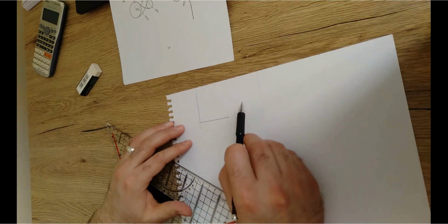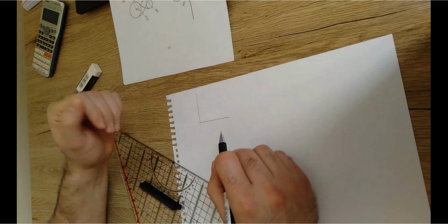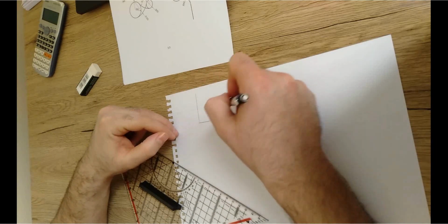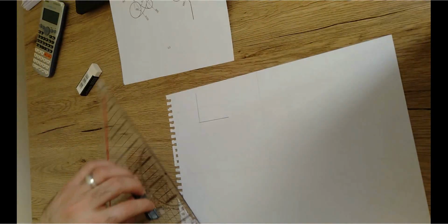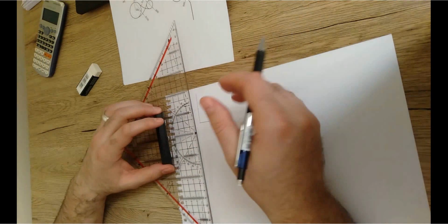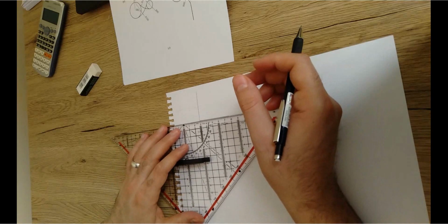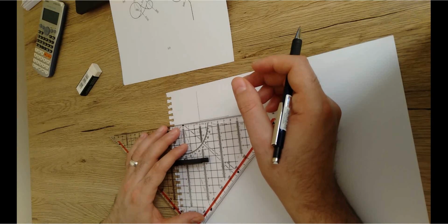This very light line is one locus of the center point of the curve. It means the center of the curve should be located somewhere over this line, but where exactly we have no clue. We're going to get it exactly from another locus, which should be parallel to the other line. So I'm going to measure 20 millimeters over the horizontal line as well, in this way.